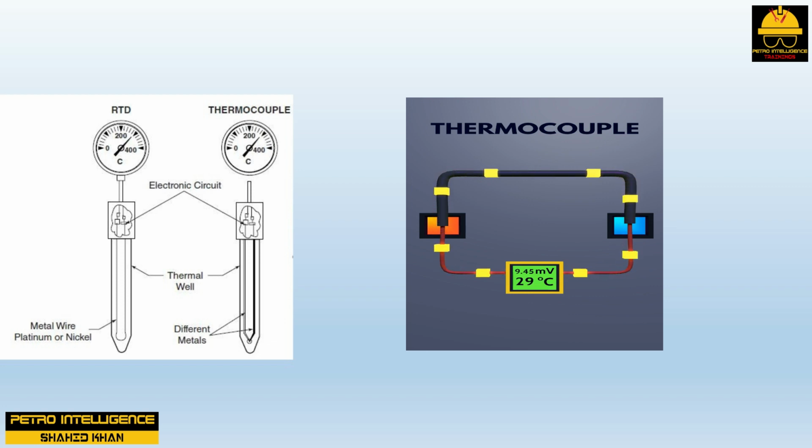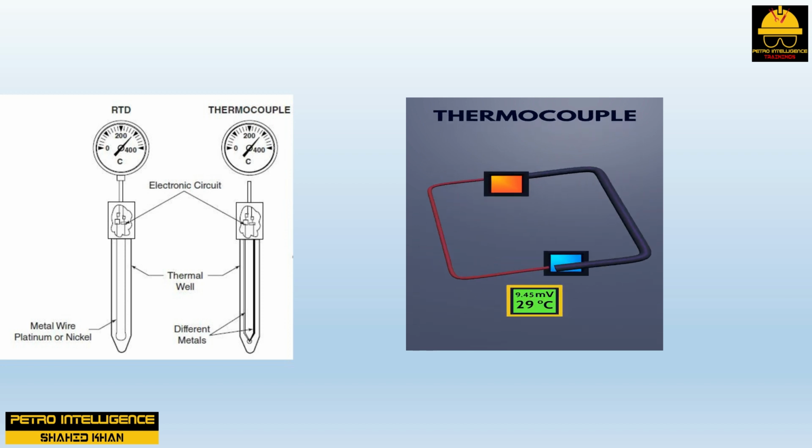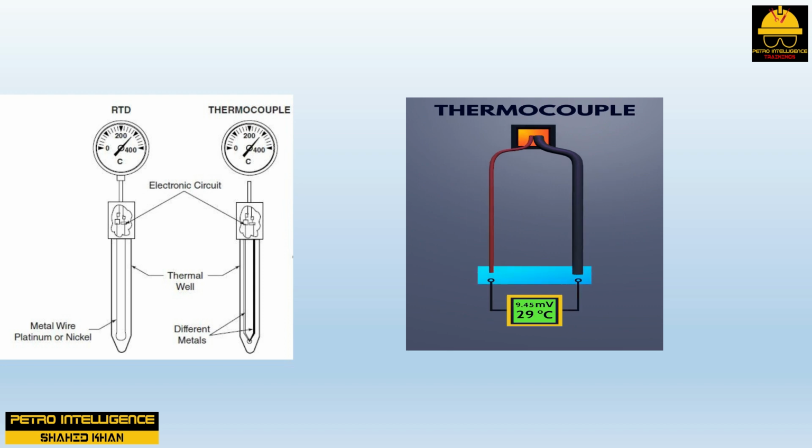Thermocouples are composed of two different types of metal as shown in the picture. A thermocouple is designed to convert heat into electricity. When heat is applied to the connected ends of a thermocouple, a low-level current is generated. The higher the temperature, the greater the current generated. Electric current is detected easily by the associated electronic circuit and is converted to a corresponding temperature scale. Thermocouples come in several types. J-type and K-type thermocouples are the most common. Type K is preferred for higher temperature measurements.